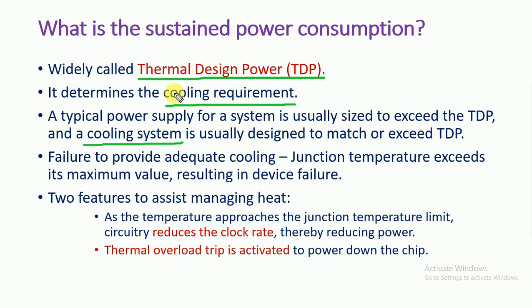So it can actually exceed the thermal design power, but after exceeding that, sometimes we can see the fan working and sometimes the fan switching off. According to that cutoff, or based on that TDP value, the cooling system must be active, and accordingly we can control that additional consumption of power.